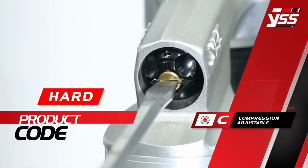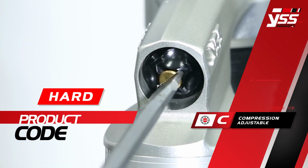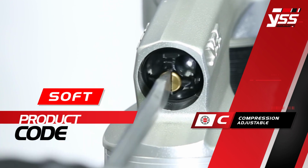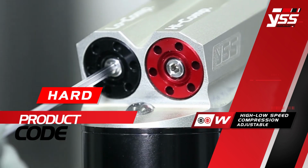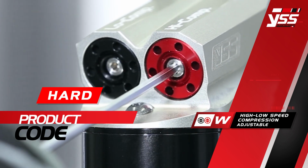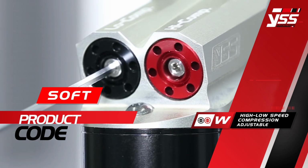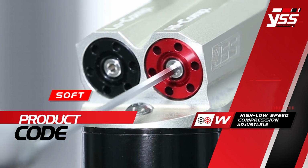Compression adjustable. C: Compression adjustable to control the ingoing motion of the shock absorber, which is divided into 2 types. Low speed, using a needle to control oil quantity from the tube to the gas reservoir as needed. W equals high-low speed compression adjustable. It is the ultimate compression adjustment developed from low speed, designed to allow the oil to flow through the control knob. This valve set will operate when the oil pressure is too high for low-speed compression to handle when the vehicle has a heavy bump. It prevents the vehicle from hydraulic lock.